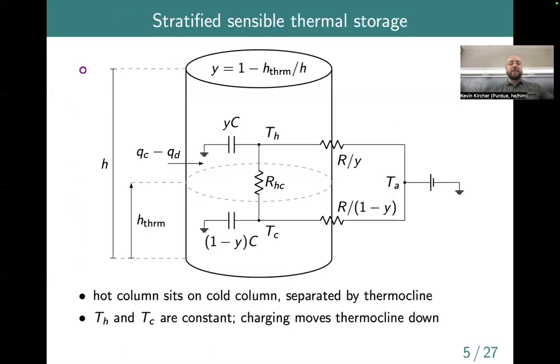Anyway, okay, so that's the lumped sensible, meaning, again, one temperature everywhere inside the tank. A slightly different version of this, but a similar idea, is what's called stratified sensible thermal storage. And this ends up being sometimes a better model when the storage medium is a liquid rather than a solid, because due to natural thermal buoyancy effects, you'll tend to get a little bit of stratification inside something like a water tank, where you get hot water up top and cool water in the bottom.